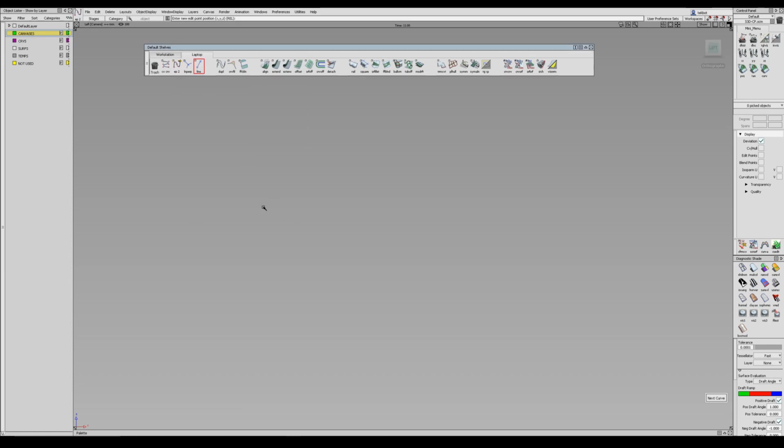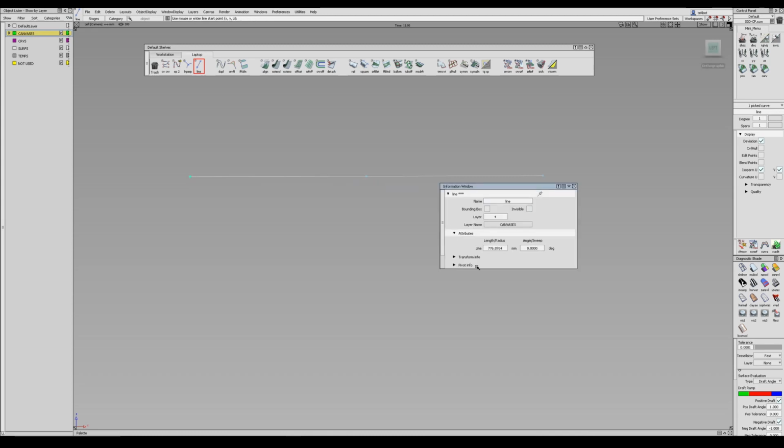And then the line curve, I use that almost like a dimension tool. You can drag it out and it gives you a numeric readout of your units. I'll use this for measurement, or let's say I needed to make something 775 millimeters long. Great, I just type that in and the curve will adjust to be that length. So, 500, it will reduce now to 500 millimeters. So I use this as a layout or to control dimensions of the objects that I have in my scene. Those two functions for curves are amazing.